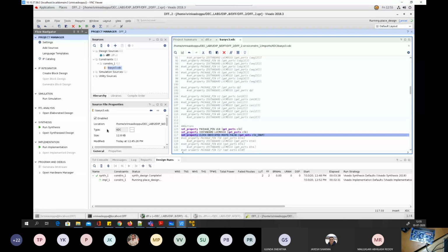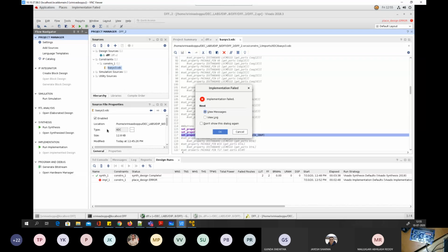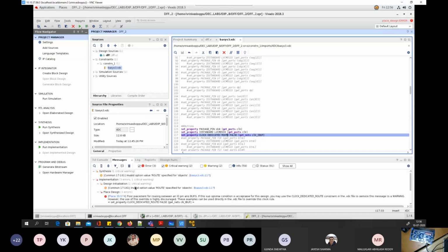Similarly, in the place and route step also, you may have a small design which can fit, but you have too many connections between these cells or gates, and then I'm not able to find the connections between these points. Logic wise I'm able to map your design, but in terms of the routing, the signal connections, I'm not able to find enough resources for routing. Then that time also it will fail. Okay, let me see. So what is this error?